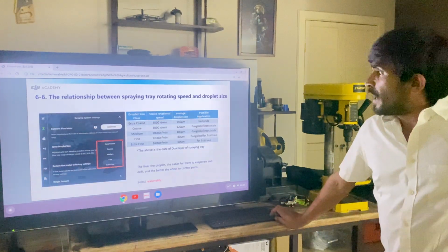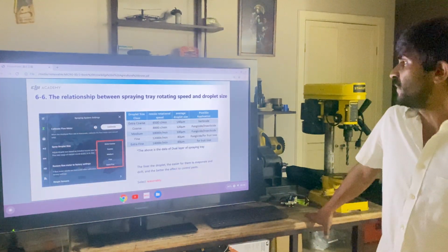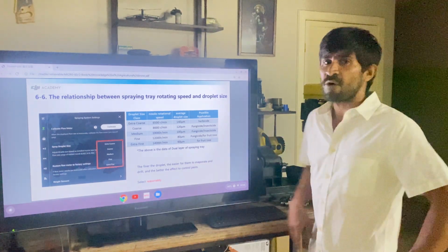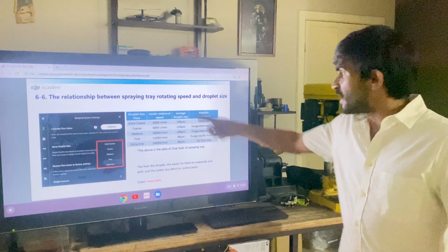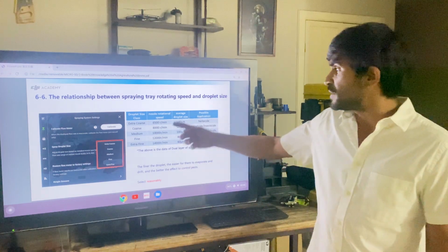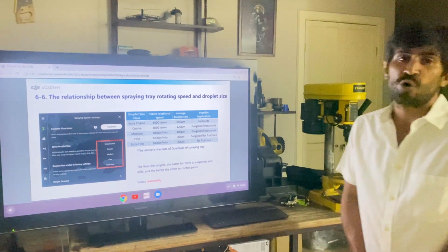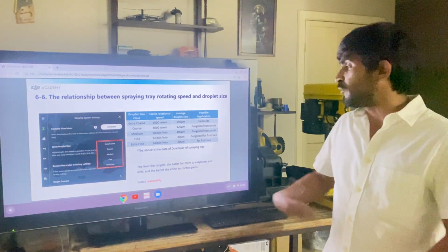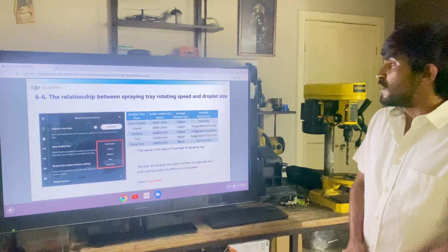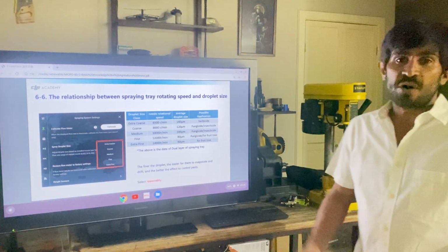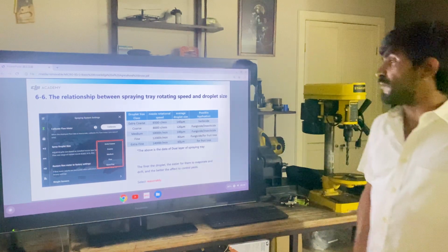All right, and here we have the table on the rotating speeds. As I mentioned, in the T40 you can now change the average droplet size by changing the speed, which you can do easily in the remote control, during flight, during a mission. For example, if you're spraying fine and you see there's a lot of wind, you can jump to medium for a while.